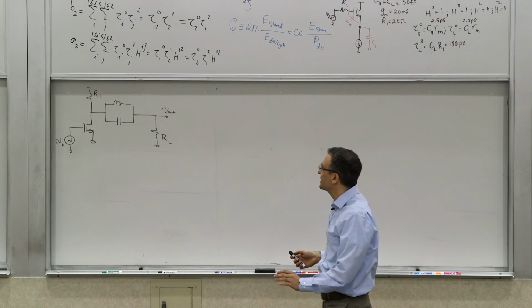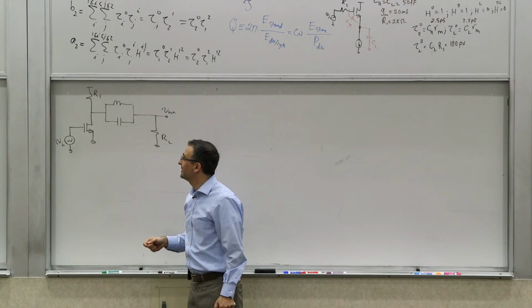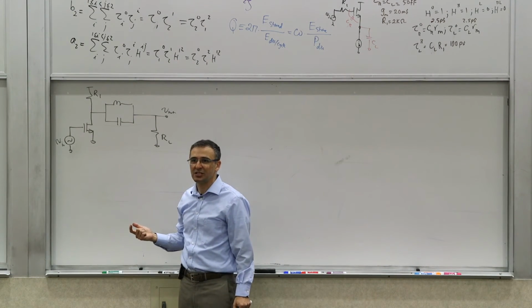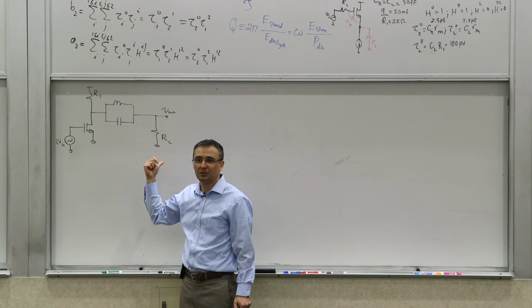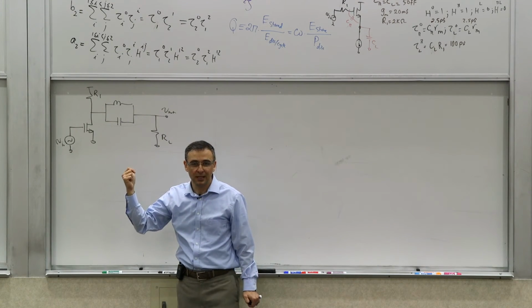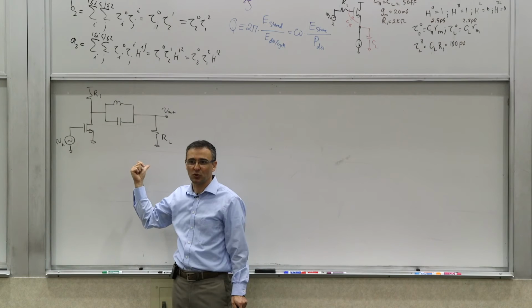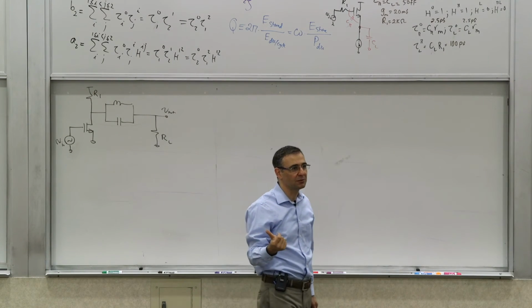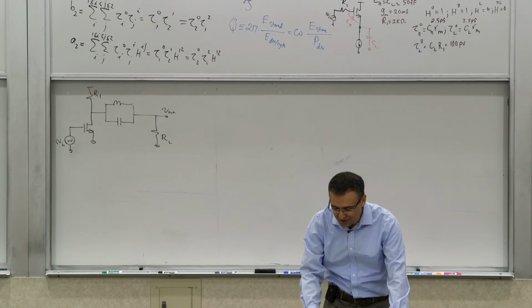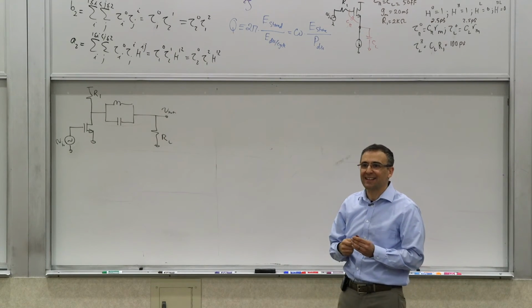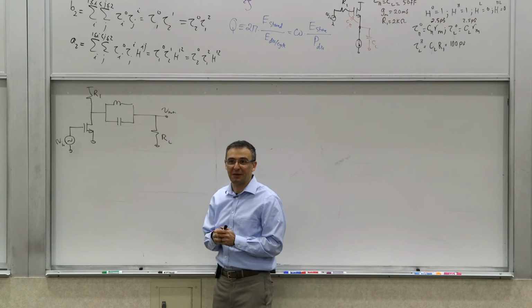We can look at it and we can see what is the transfer function at DC, at 0. At 0, do we get something through? Yes, right? Because you have the inductors shorted. At infinity, do you get something through? Also, you get something through. So it's an interesting circuit, right? There's some frequency at which something may not go through.